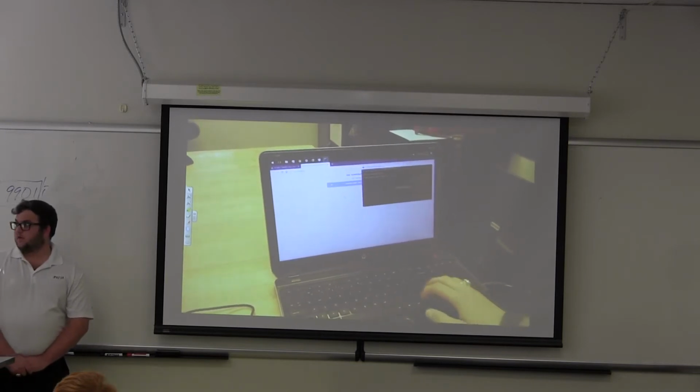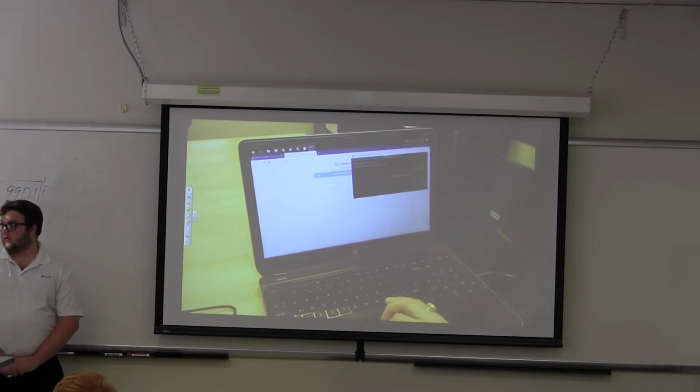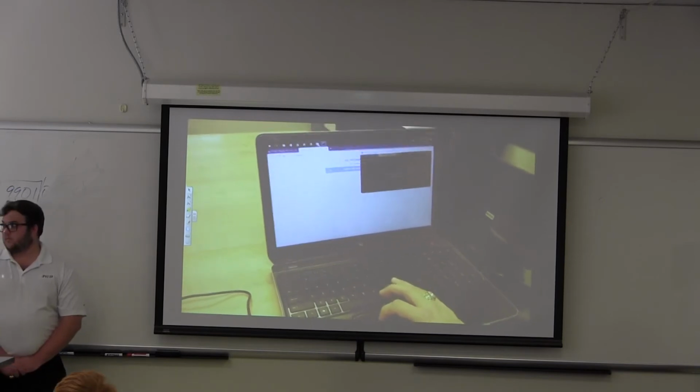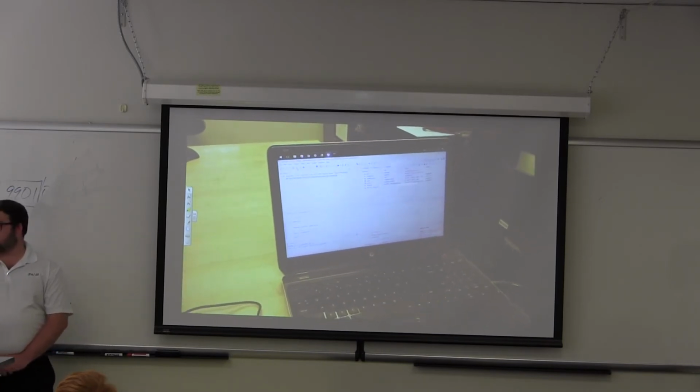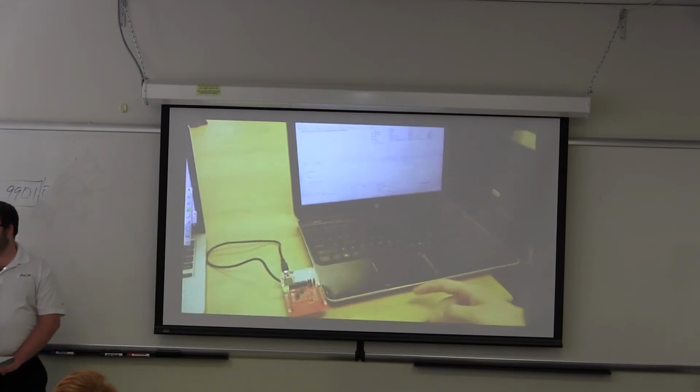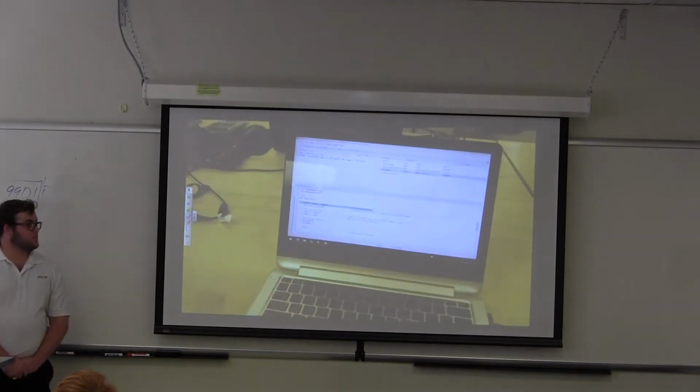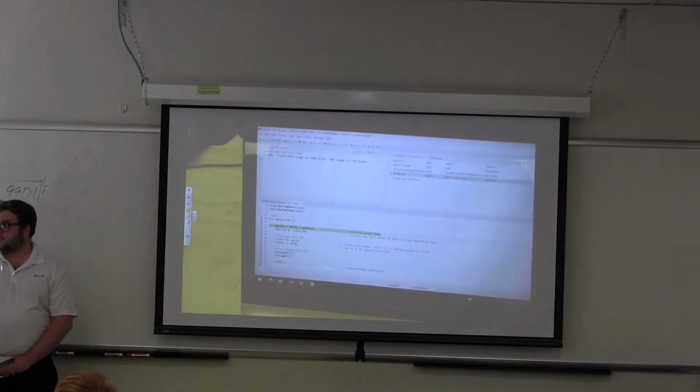We will begin by starting the COM port listener. It started. Next, we start the RF listener. The CC1310 is now waiting to receive. We're now going to begin sampling voltages and transferring the data over UART.